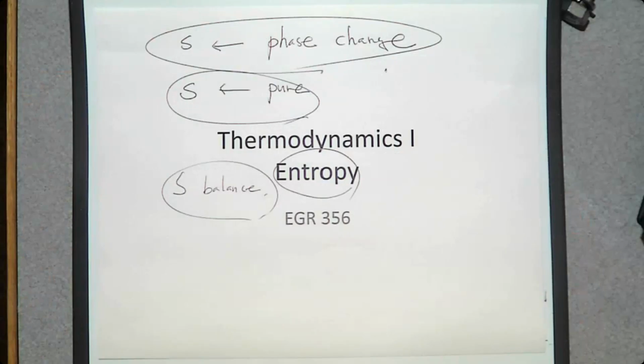Entropy is a thermodynamic property that shows how much waste energy is in your system. So for the same system, one can have higher useful energy than the other. Then the other system has higher entropy, even though the total energy is the same. The simplest way to understand this: what if you have 100 kilojoules of electricity?